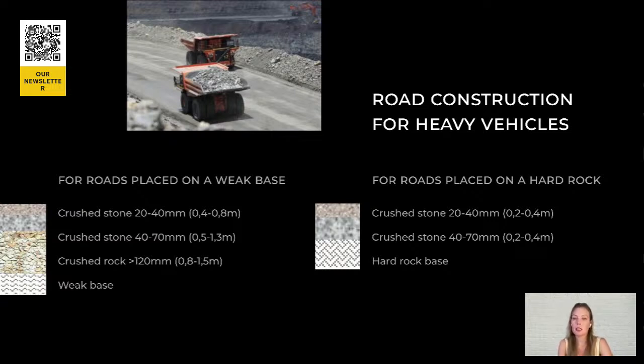So here you can see the most common rock size ranges used for building roads for heavy-duty dump trucks. Sometimes we determine the foundation thickness through trial and error. Special attention should be given to the top layer, which directly contacts the tires. This layer must meet regulatory standards for parameters like flakiness, angularity, and wear resistance.